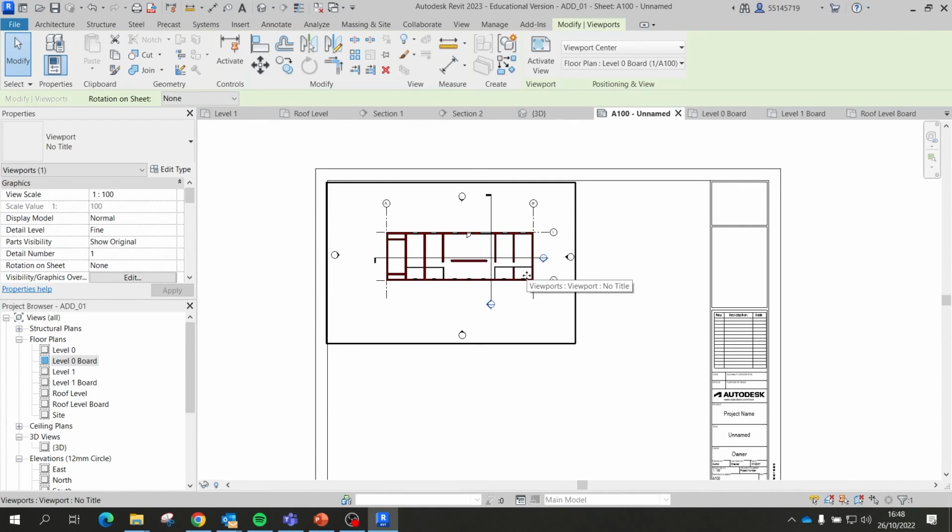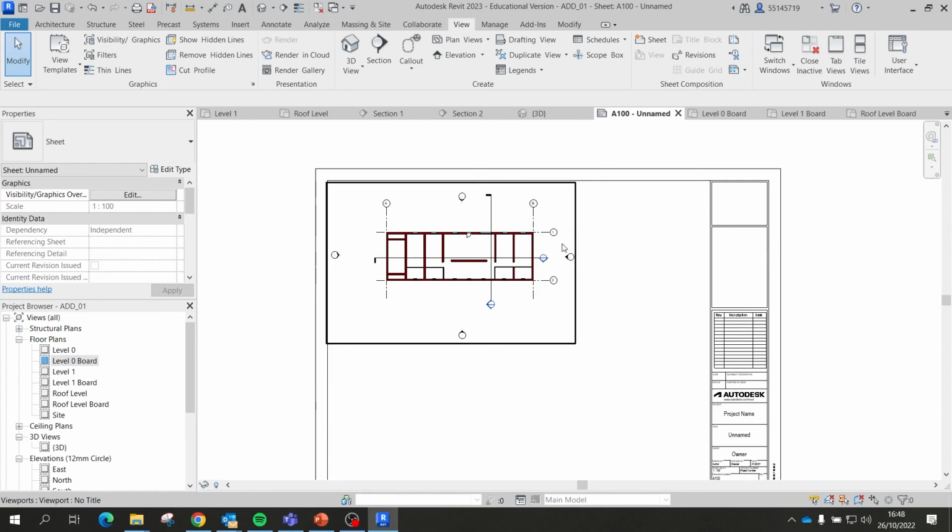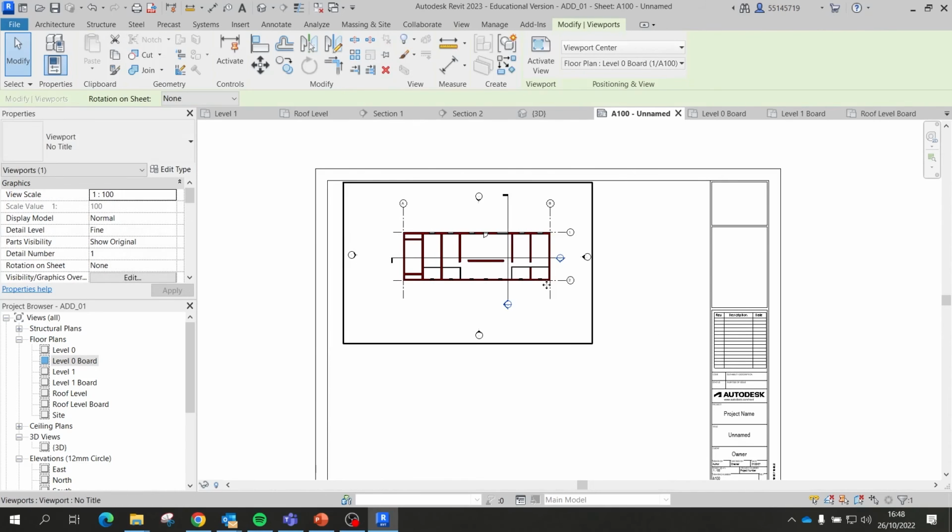And keep in mind that this is like a sticker at the moment. If I want to get in the view and activate it, I just need to double click on it, and so I'm now acting on the view. So whatever I'm doing here will have an immediate effect on the actual view. If I double click in the emptiness, I'm deactivating the view, and I can keep dragging it around and organizing these as a single drawing.